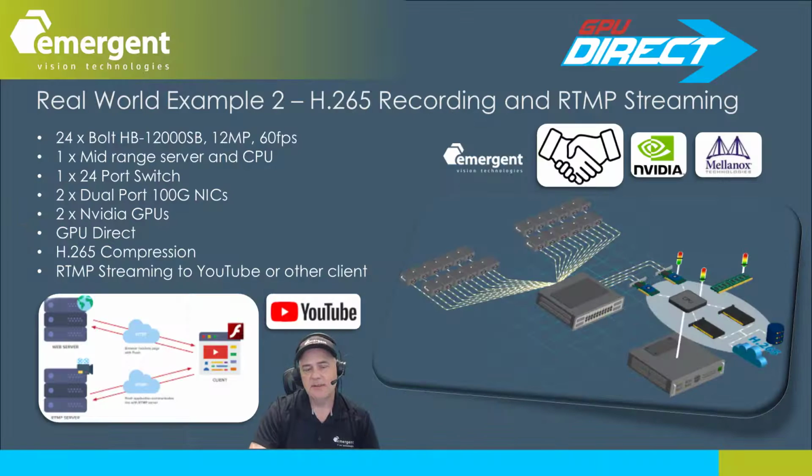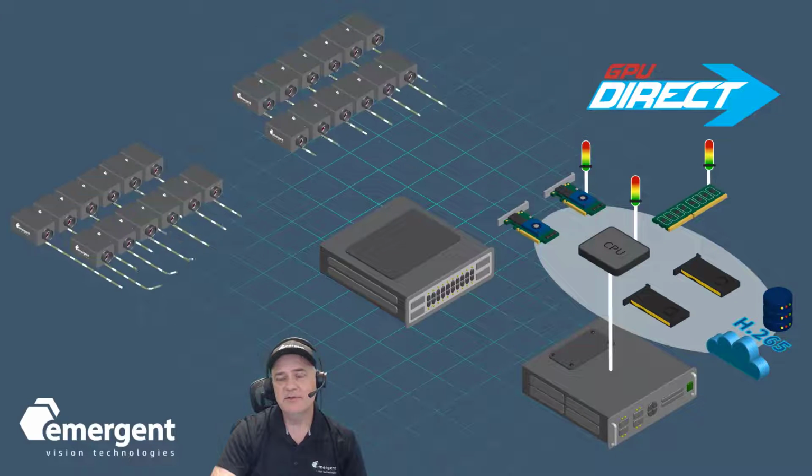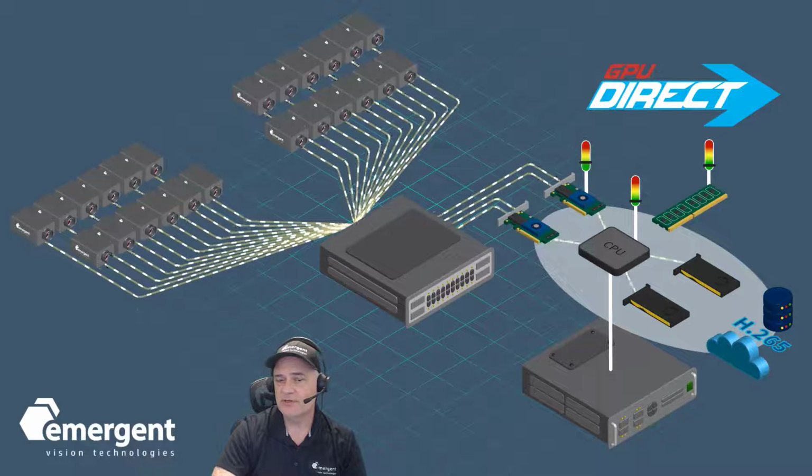This is another real-world example which uses the same camera setup of example 1 but uses GPU Direct to send the camera data directly to GPUs, which performs H.265 compression, and the compressed images are stored locally on disk, as well as streaming using RTMP to clients like YouTube. At 30 frames per second, we are running this system with as many as 48 cameras, using a 48-port switch, while still running on a single mid-range server and CPU. This short animation illustrates the flow of data in such a recording and streaming system.